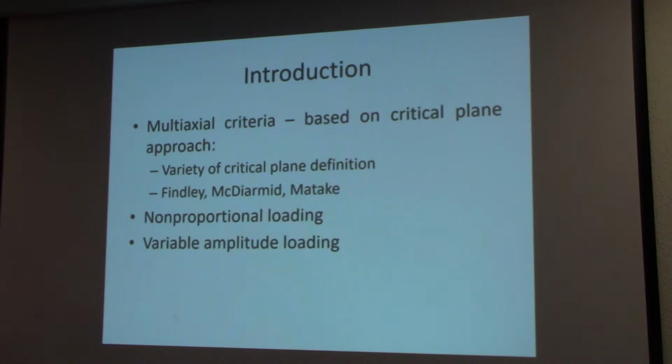Okay. So today I will be dealing mostly with only three critical problems during the lifetime estimation under complex loading: choosing the correct multiaxial criteria, the way to process the non-proportional loading, and of course the variable amplitude loading effects. In this case, it will be only in the form of a damage accumulation rule.